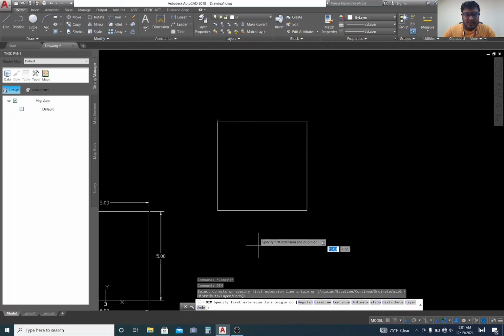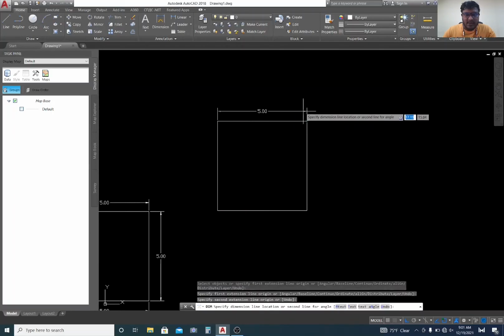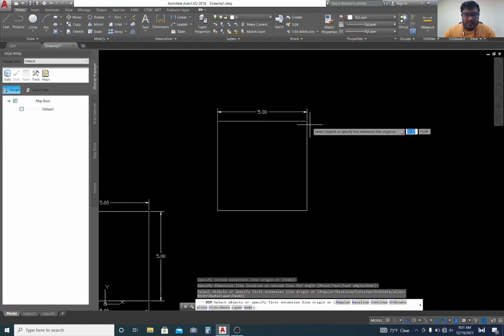Okay, just press this corner to this corner and drag it up. We have to do this from our right side, right click the mouse. See, in this dimension command, we don't need to press the space again and again, because AutoCAD automatically reactivates after our dimension is finished. AutoCAD automatically understands to continue our dimensioning process. Now it's asking again to specify the first extension line origin.